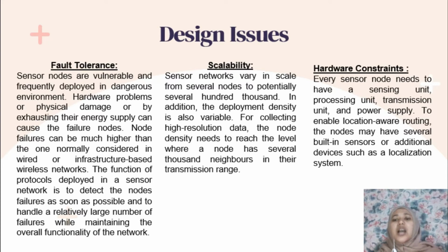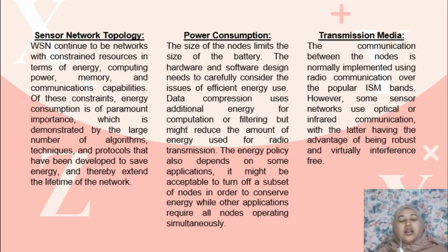There is a hardware constraint. Every sensor node needs to have a sensing unit, processing unit, transmission unit, and power supply. To enable location-aware routing, the nodes may have several built-in sensors or additional devices such as a localization system. However, every additional functionality comes with additional costs and increases the power consumption and physical size of the node. Okay. Fourth is